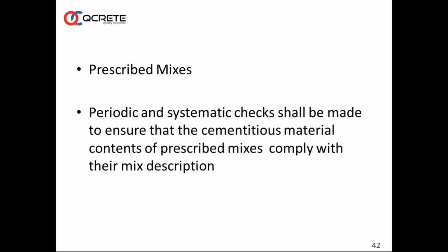Prescribed mixes. See here, what happens is when we are talking to a ready mix company, one option is to ask them to design the mixes based on their experience, the data available, and things like that, and give the specifications that I need this concrete for moderate exposure or severe exposure or this kind of intended use. I want 7 day strength like this, 28 day strength like this, or 3 day strength like this. All these specifications you give, and give the freedom to the ready mix company, concrete technologist or the designer to do the design.